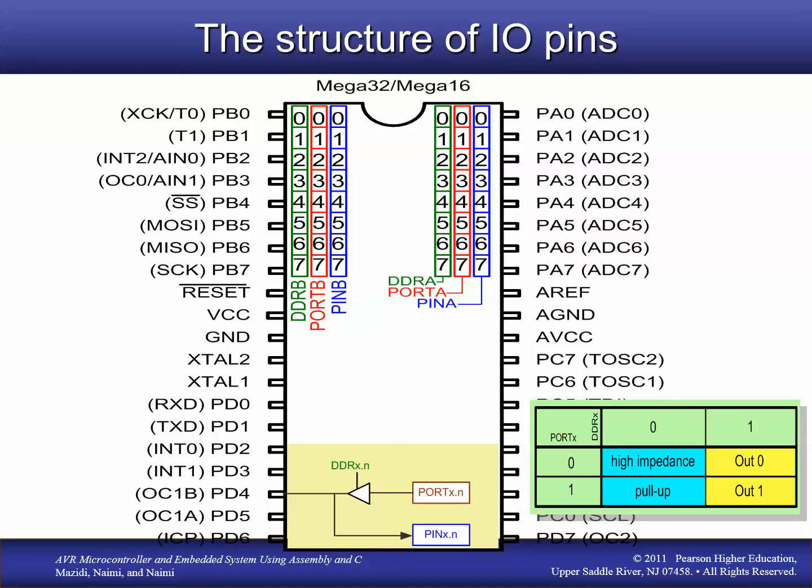For example, if we have a switch that connects a pin to ground or not, then that pin would be an input, so data is going into the microcontroller. An output would be used to control some kind of actuator or a light. An output would be sending data out, so we could connect an output pin to an LED, and then write a program to turn that LED on or off. So that's called an output pin.